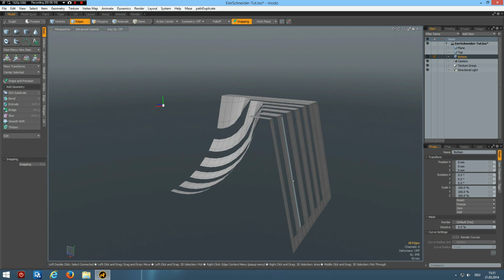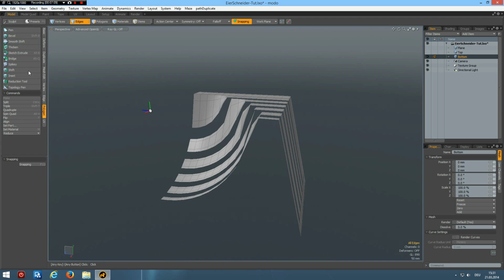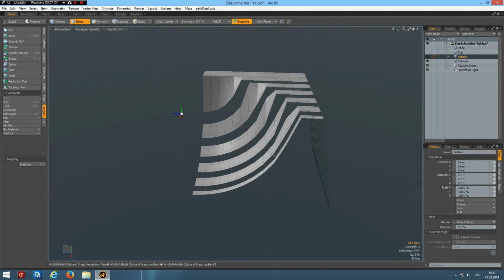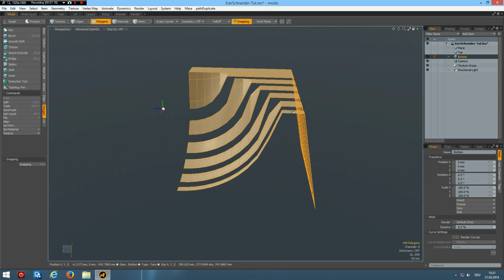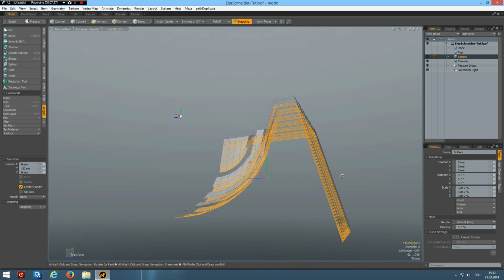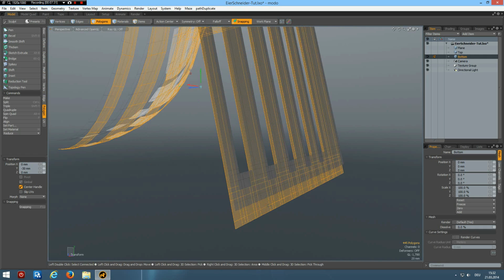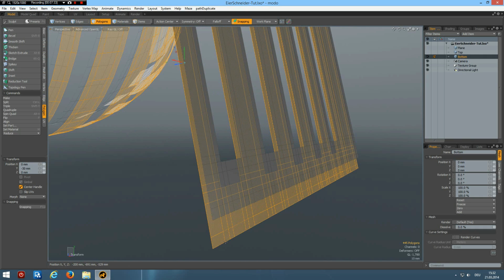You can try to use the thicken tool, but I think you will not get happy with that. So I'll do it the old way. Control copy, Control V, W key, bring the copy down, minus 30, yeah, why not? Now we have several areas which are a bit of a problem. The first is here. The bottoms are not aligned, so let's do this first.